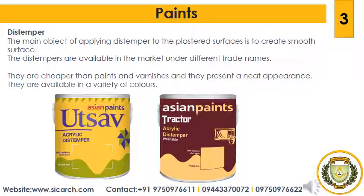So a distemper is composed of a base, carrier, coloring pigments and size. For base, the whiting or chalk is used and for carrier, the water is used. Thus it is more or less a paint in which the whiting or chalk is used as a base instead of white lead and the water is used as a carrier instead of linseed oil. So the distempers are available in powder form or paste form. They are to be mixed with hot water before use.